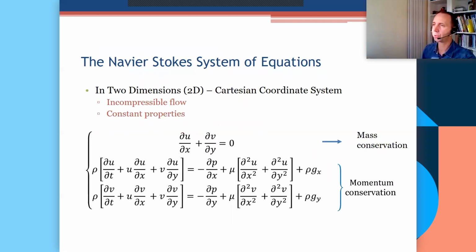These governing equations, called the Navier-Stokes equations, as seen here, appear reasonably complex at first sight. And these are only for what we call incompressible flows, so certain simplifications were possible. We assume constant flow properties, that is the density is outside of the derivatives. So is the dynamic viscosity. You've got the density here.